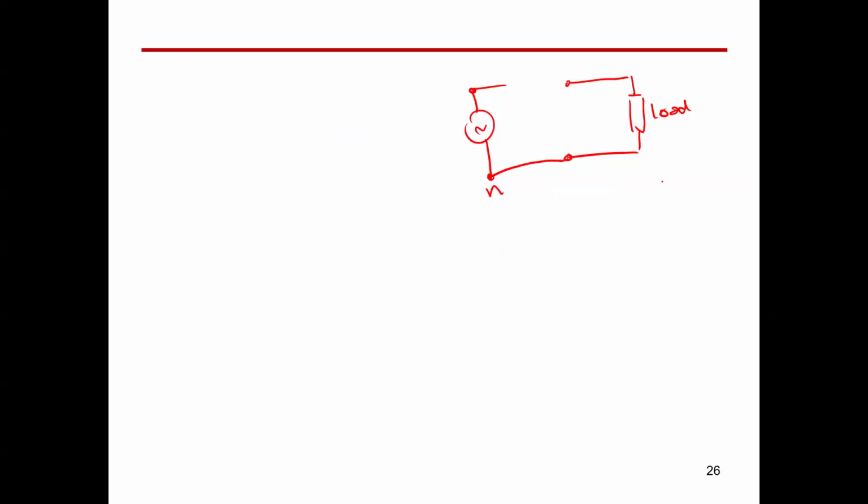You know that if I'd like to measure the current, I can add an ammeter in series. If I'd like to measure a volt, I need to add a voltmeter in parallel. What about the wattmeter? Or how can I measure a power? Power can be measured by a device called wattmeter. So the wattmeter, guys, internally has two coils. One coil connected in series to measure the current, and another coil is connected in parallel to measure the volt. So this is the device which is called wattmeter.